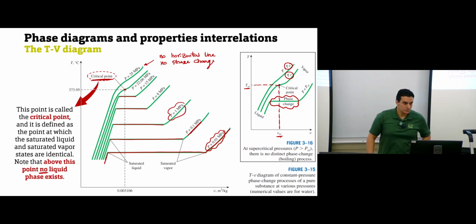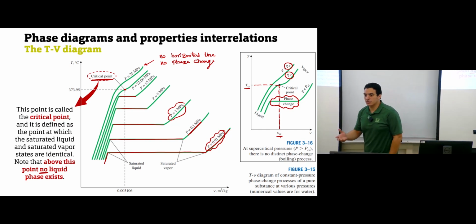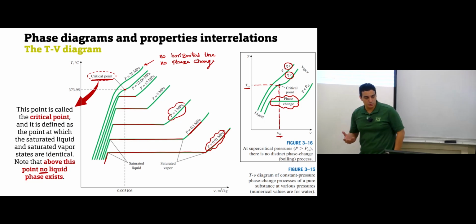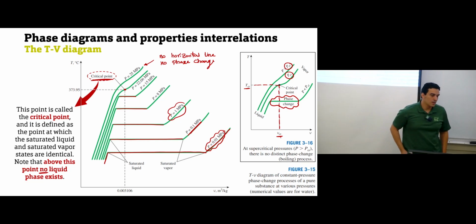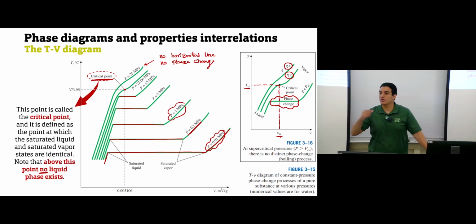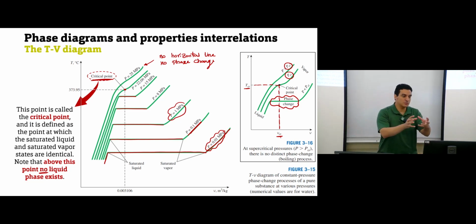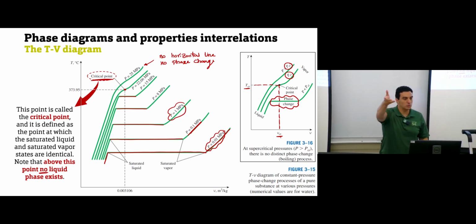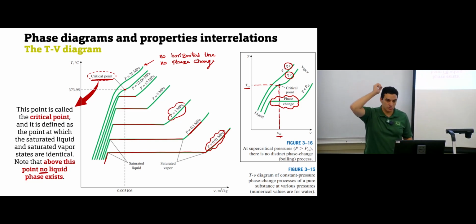Okay. So let's assume, for example, you are using the distillation process. Distillation is one of the unit operations you use to separate mixtures based on the boiling point. So you have a mixture as liquid. You put this liquid mixture in a distillation column. You try to heat it, then you convert the liquid to vapor and separate the liquid from the vapor.